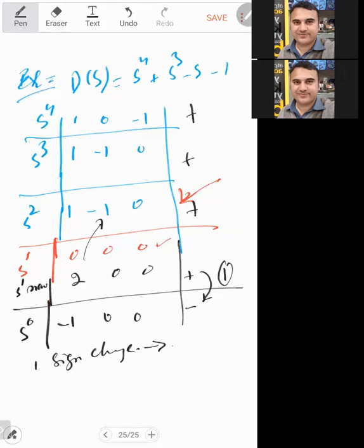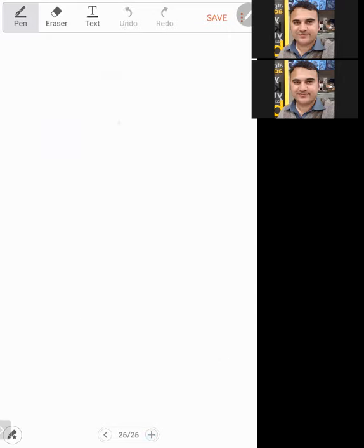So there is one imaginary pole. And if we have one imaginary pole, which side is it on? The auxiliary polynomial gives one sign change, so one pole in the right half plane. There is no other partner of this.